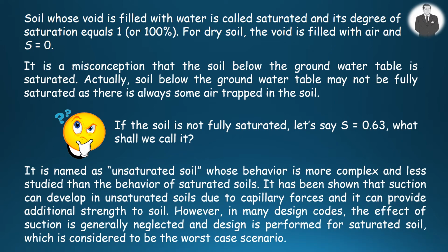It is called unsaturated soil, whose behavior is more complicated and less studied than that of saturated soils. It has been shown that suction can generate in unsaturated soils because of the capillary forces, and it can give additional strength to soil. However, in many design cases, the effect of suction is usually ignored, and the design is performed for saturated soil, which is considered to be the worst case scenario.